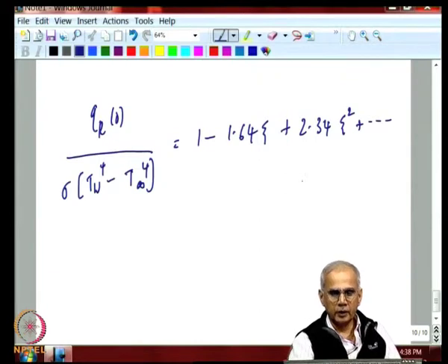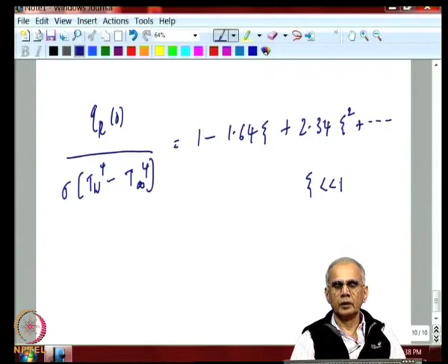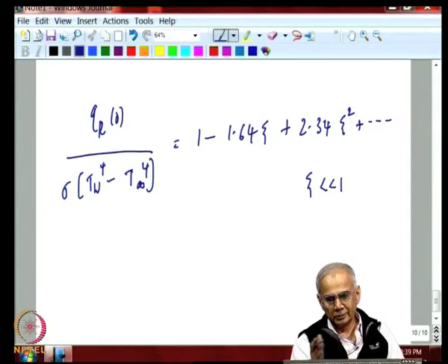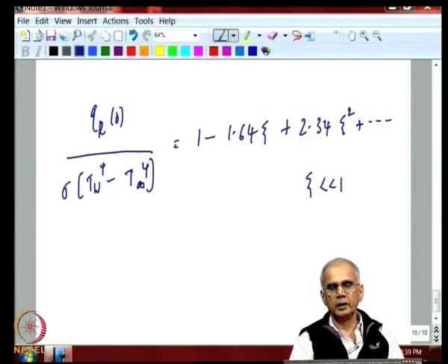Again, notice this is valid only for psi much less than 1. So, again it takes psi as around 0.1. You can see that when there is a gas and there is convection playing a role, the radiated flux of the wall will reduce at small psi.